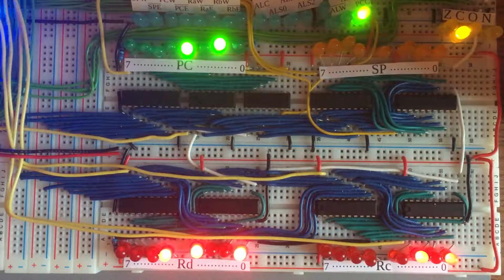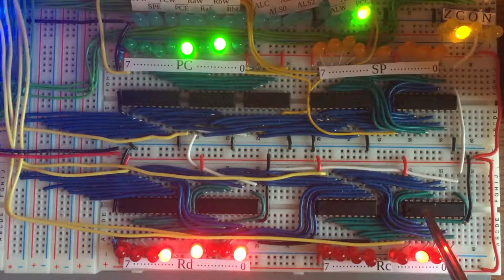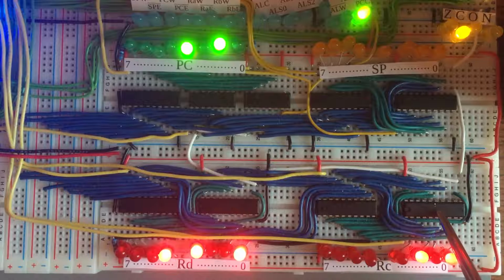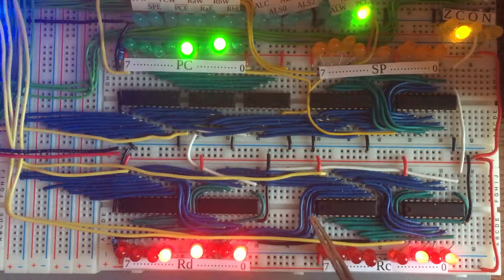And more importantly, it actually allows me to put 2 registers on a single breadboard. And so we've just had a look at the D register, but if you have a look at the C register, that works in exactly the same way. So that too has a 74HCT245, which enables whatever is being output by the register, which is a 74HCT377 for the C register. So in this case, it's a 5 that's being output on all of these green wires. And so that will be output onto the blue wires, which are the bus wires.